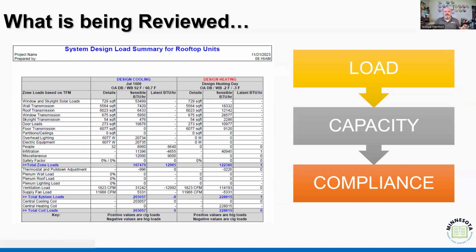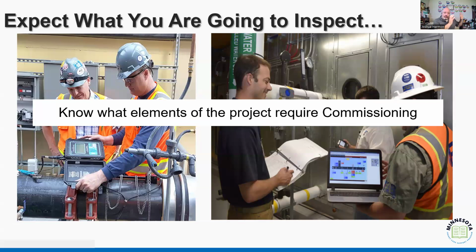The same thing happens when it comes to the actual installation process. I, as an inspector, am there to make sure it's installed properly. It's installed safely. I'm not running around the building, the entire complex, making sure that every room gets the adequate amount of air pressure, all right? That all those systems are working together effectively. That's where we have, again, this verification, testing, commissioning process. The expectation is that someone is going to verify that we're getting 430 CFMs of air in this duct at this location.